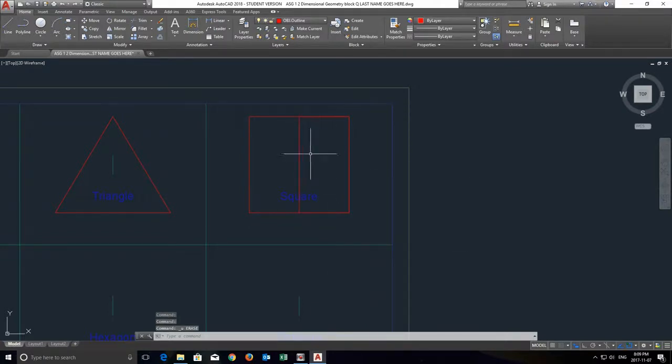There. Had to do that twice because I used that command twice. There is a list of commands, and you can undo as many as are saved there. Okay, so now I want to take my rectangle and I am going to copy it. Or actually, I'm going to move it. Now, I need to move it, so I'm going to select it first, press enter.